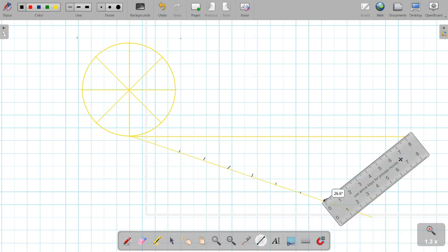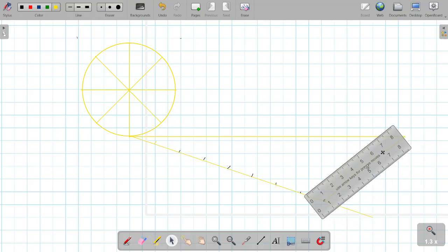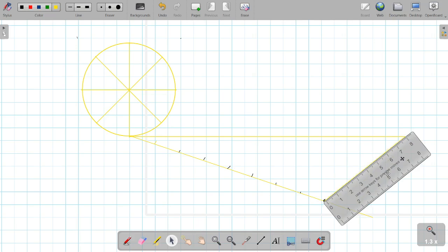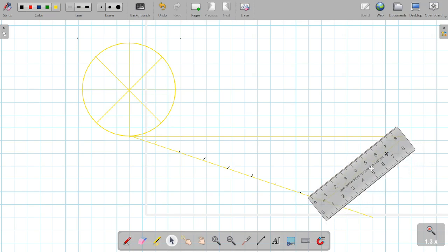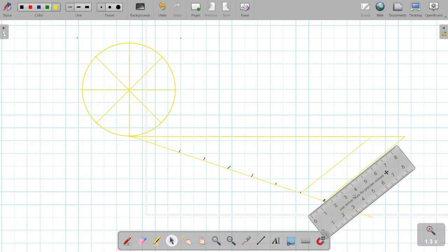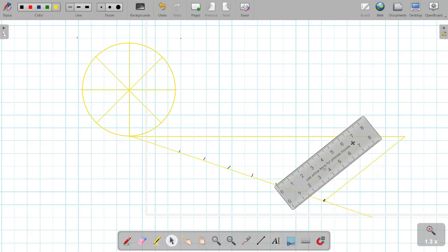So last point connected to the last point. Then just by moving the scale parallel, make the lines. For example, this we have to make parallel to this point and then draw a line. Then moving it to the next point. The scale should be parallel.